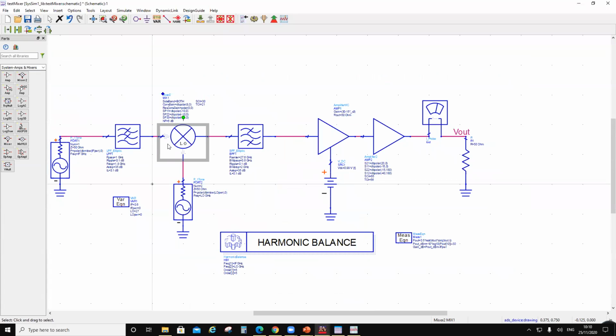If you put lots of harmonics into a communication system, anywhere else, if there is mixing involved, those components would come back to your IF or your frequency of interest, because everything folds. Whenever I do up conversion, the frequencies fold over each other. So if you put harmonics into the chain, due to some non-linearity of this amplifier, those components will come back.